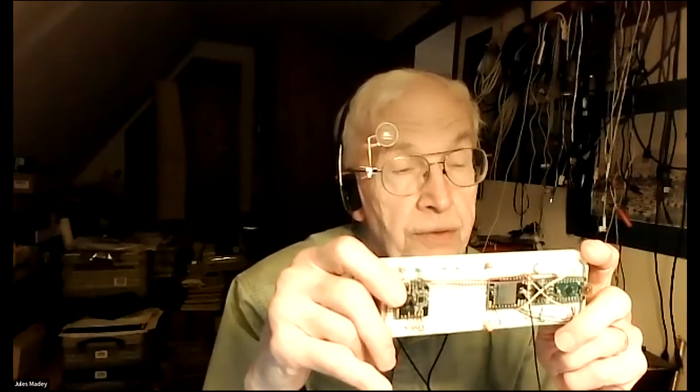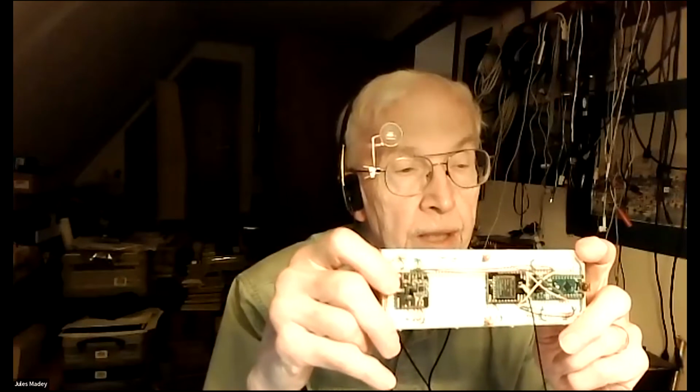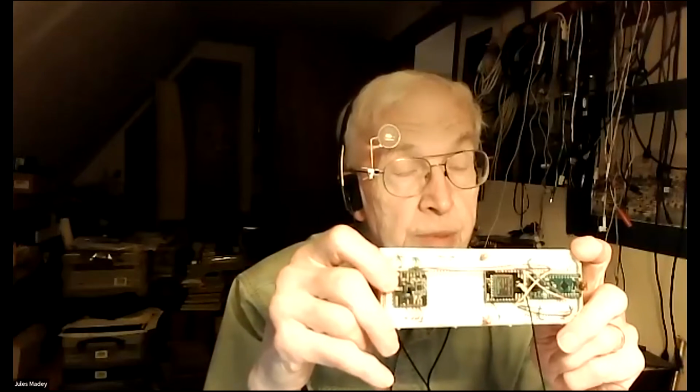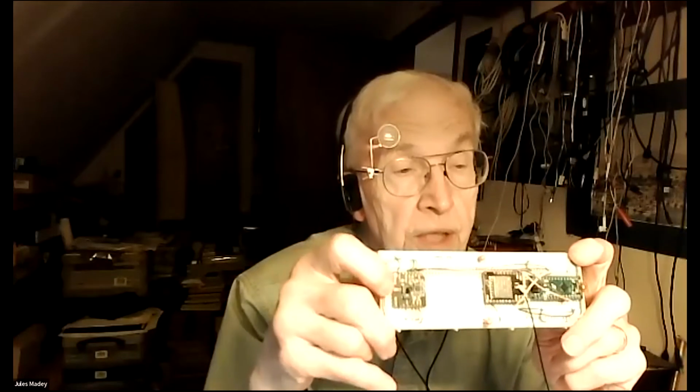The whole thing, when the LoRa is not transmitting, the current drain is, and this is not going into sleep, this is just continuous, 13 milliamps. And that's on a 3.3 volt supply. So that's about the lowest we've been able to get to so far, and would make a fairly nice portable installation to run for a few days or maybe a few weeks, depending upon the battery size, transmitting data back to a local location over LoRa. That's pretty much it from here. I'll turn it back to Nit.